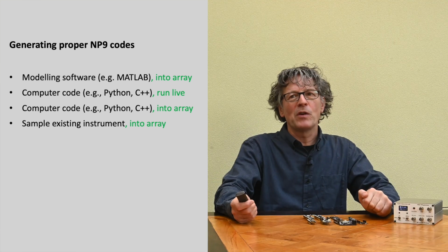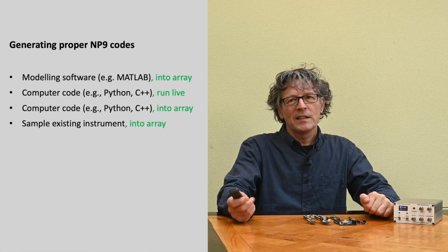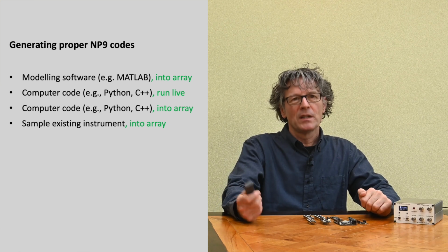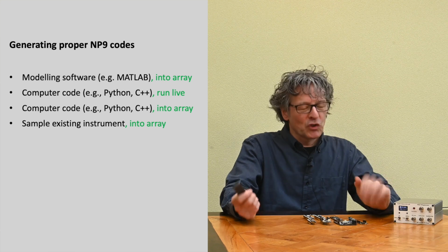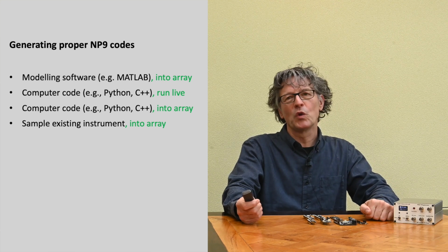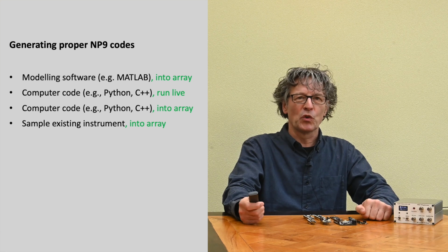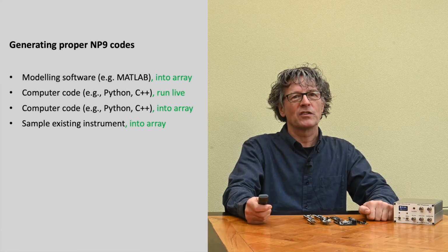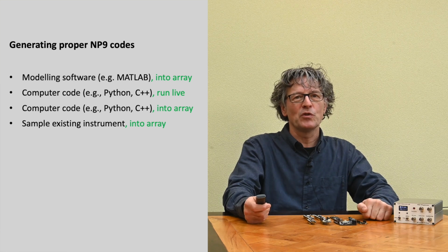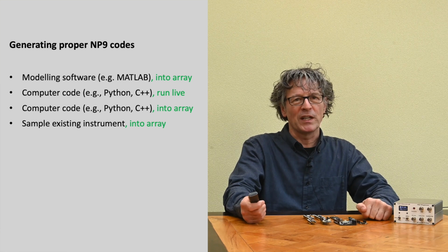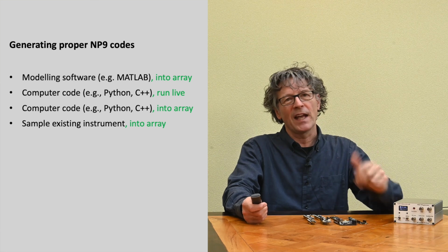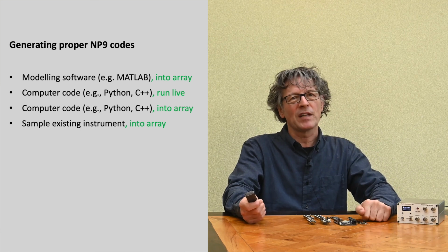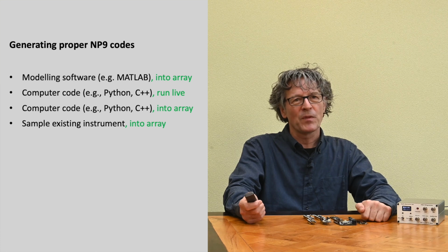Now, how are we going to go about capturing this signal? What I did is actually use an oscilloscope to do this capturing part. And well, most oscilloscopes, as you will know, have serial protocol decode, and many of them actually also have a parallel bus decode function. And it's the parallel bus decode function that allows you basically to do this type of capturing. So I took an oscilloscope and I connected the signal that I'm interested in, the clock that comes out of the SMIQ, and the frame signal, and I inputted them in this case in a Rohde & Schwarz RTB oscilloscope.